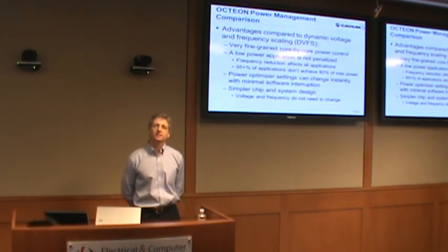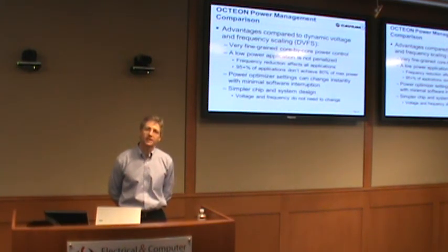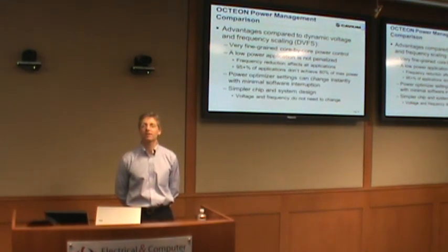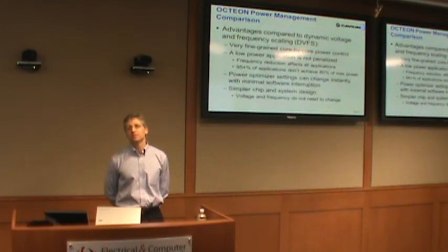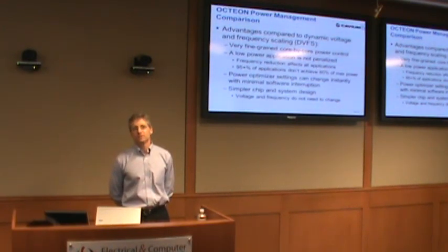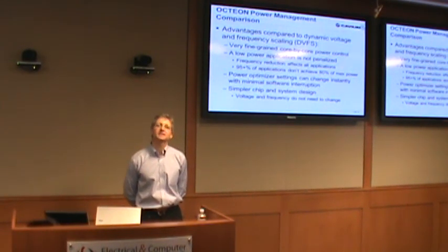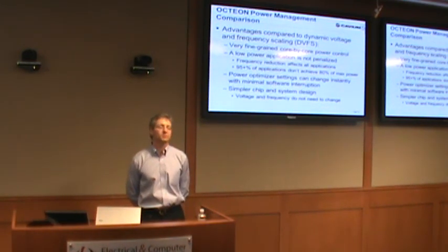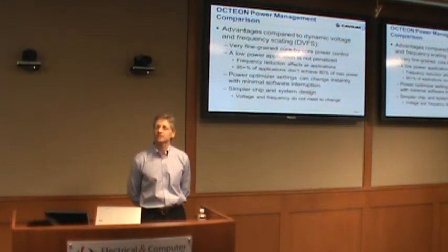And the implication here is that that's important because most applications don't consume a lot of power. This very fine-grained power control, the settings can change instantly by software just writing a register, and ultimately leads to a simpler system and chip design than a DVFS solution.